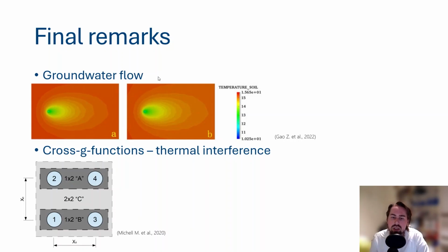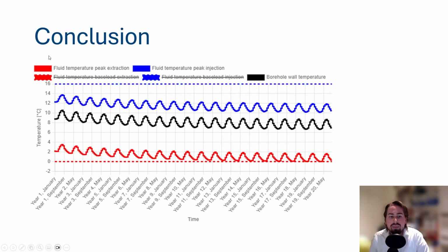So to conclude this lecture and our two-part series, we were talking about these temperature profiles, and we now know that the effect on the long term is influenced by the ground thermal conductivity, by our borehole spacing and our configuration. It has to do with the seasonal and long-term variation. It's an energy problem. Whereas on the short term, we're actually more talking about the fluid temperatures, and the borehole effective resistance is important, which is, together with the power at the very instance, the difference between the borehole wall temperature and the fluid temperature.